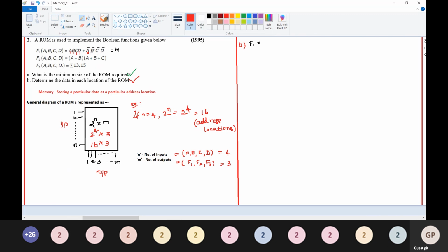So 1, 1, 1, 1. Here are all zeros, 0, 0, 0, 0. Just add the corresponding values. If it is 4-bit, use 8421. So you have 4 ones here. Add all the 4 variables: 8 plus 4, 12, 13, 14, 15. So M15 plus M0. So function F1 is nothing but summation of m of 0 and 15.